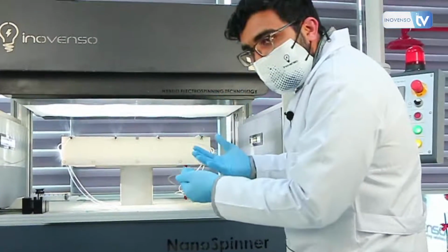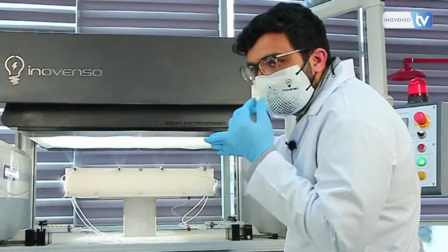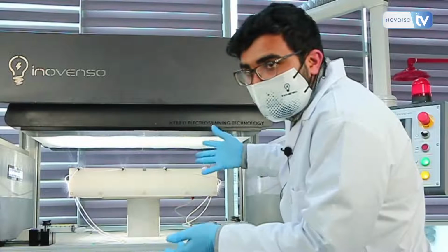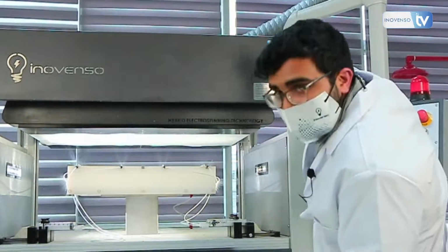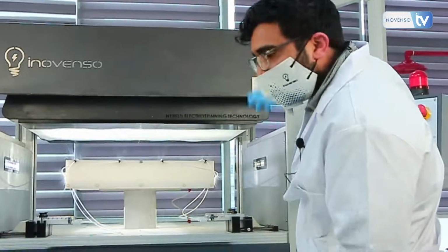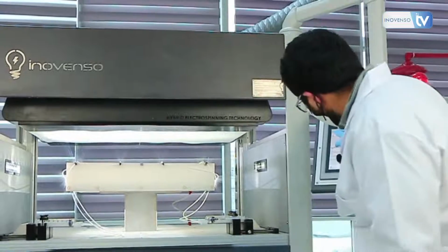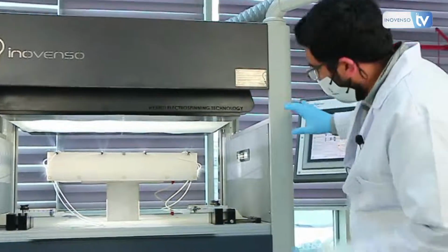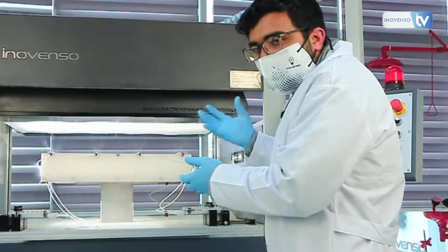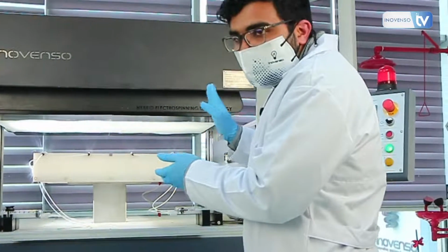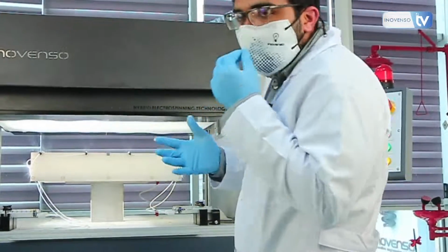In large scale production, you end up with a lot of solvents in gas form that you need to get rid of, especially in large quantities. So our machine is connected to a ventilation system. It has an exhaust fan of about 100 CFM, and you activate it from the control panel here. It starts sucking up the solvents that evaporate, and sends them directly to the building's ventilation system, just to keep the laboratory a bit cleaner.